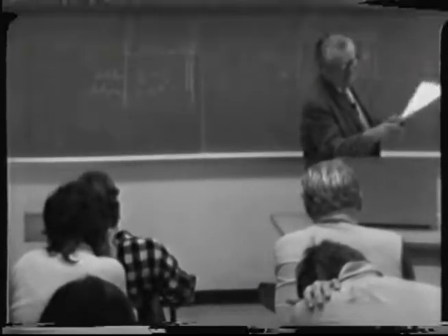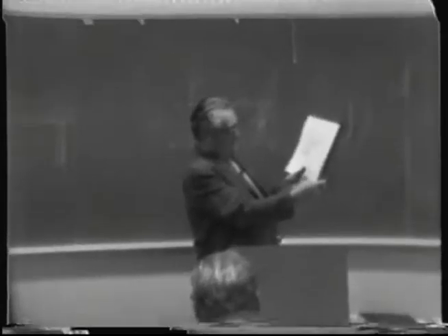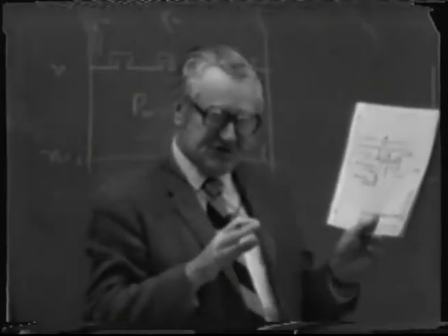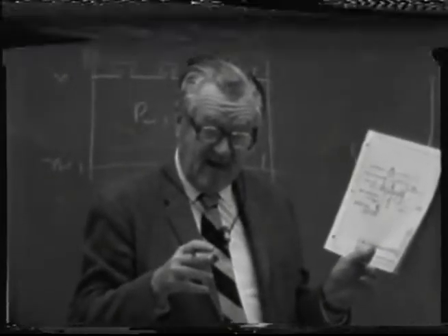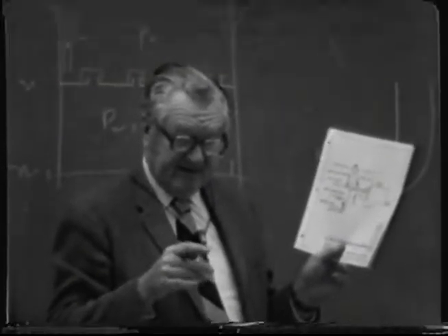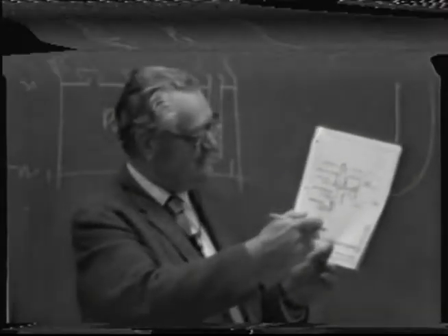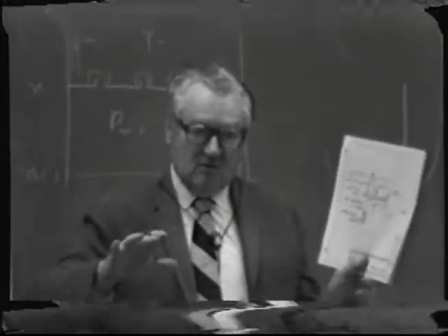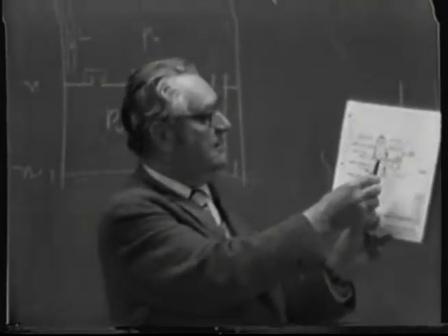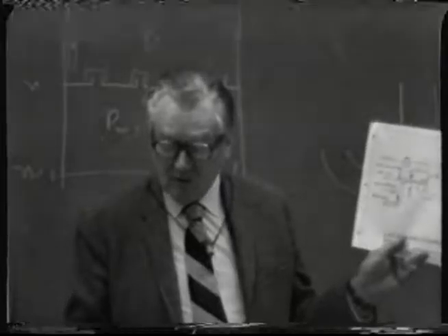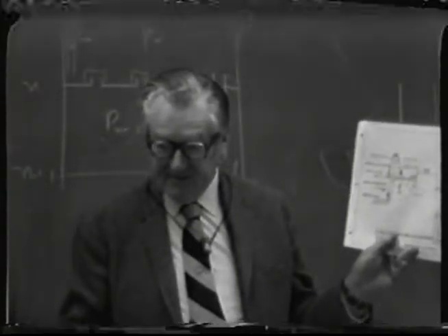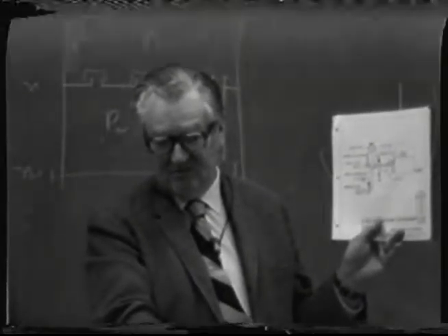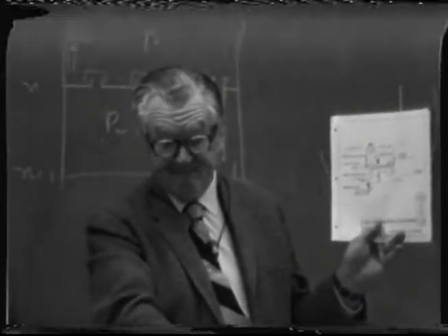Well, let me go through it again, very briefly. The expansion of the steam causes a pressure drop in this chamber, which causes some of the liquid in the stillage, essentially water at the boiling point, to flash into a vapor because you lower the pressure below the operating pressure.